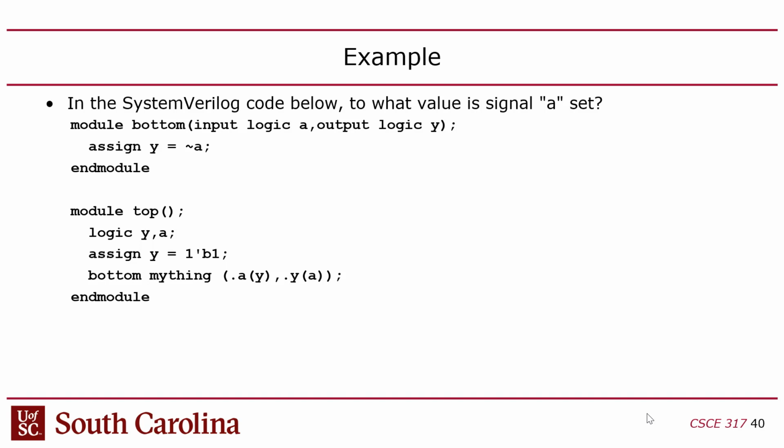But the problem is that you've got A and Y in both designs, but they are reverse connected as I go from top to bottom, right? So what's happening is that Y is A in bottom, so just think of Y as the input, A as the output, and the thing is inverting. So because I'm assigning Y, I'm assigning 1 as the input, 0 will be the output. In this case, 0, the output, is A inside of bottom. Does it make sense? Okay.